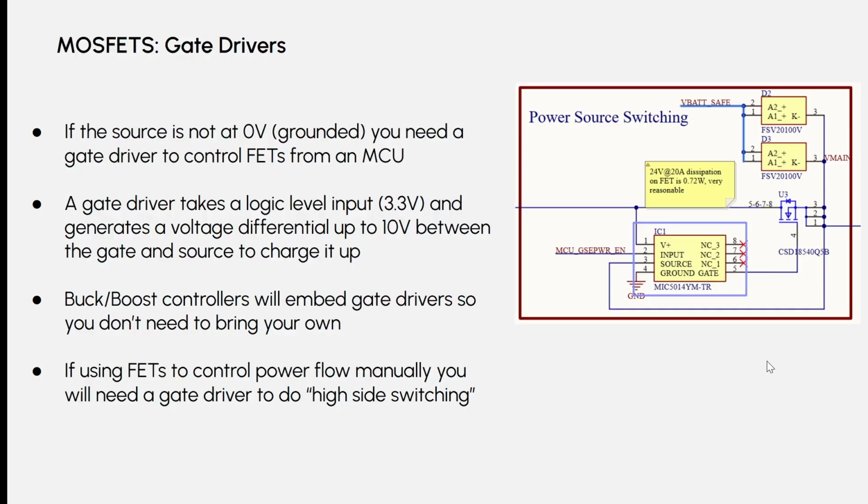The challenge is that when you get to really high powers, like 20 amps plus, the load switches don't exist. You need to make your own. So this is just something to be aware of, that when switching high voltage with a MOSFET, you might need a gate driver, and it's not going to just work if you plug it in. That's pretty much all to say there.